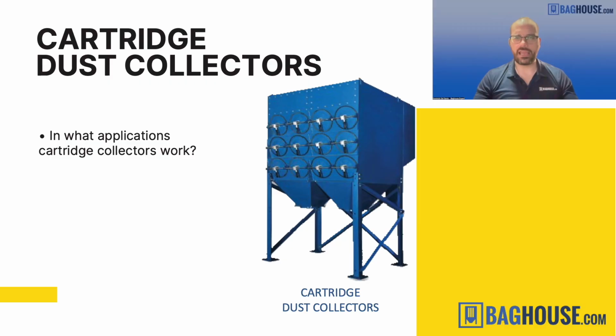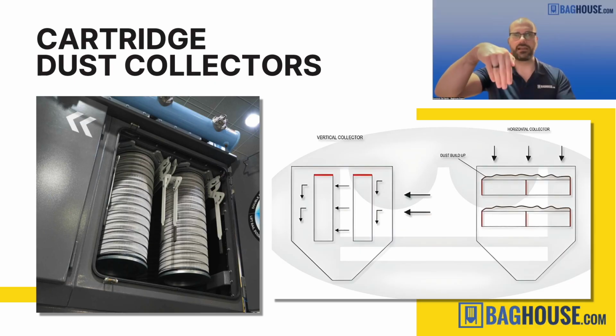Another type of collector that you can at times use is what's called a cartridge dust collector. Cartridge dust collectors are basically pulse jet dust collectors, but instead of using bag filters, we use cartridges. The picture we have here shows a horizontal cartridge collector, where the filters go in horizontally. These can be used for woodworking applications, but we have to be very careful with them. Other designs have the cartridges mounted vertically so that the dust wants to fall off naturally. Both kinds of cartridge collectors can be used in woodworking, but in certain specific instances.